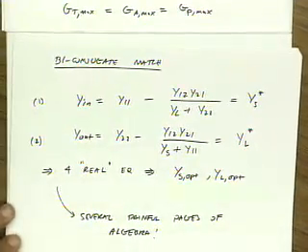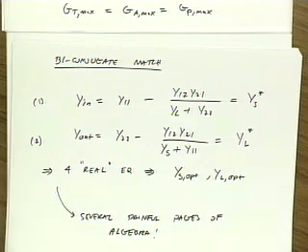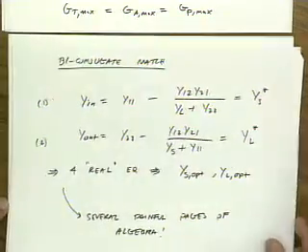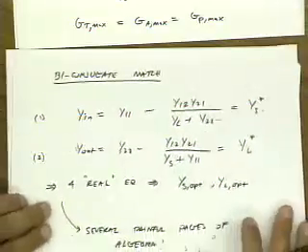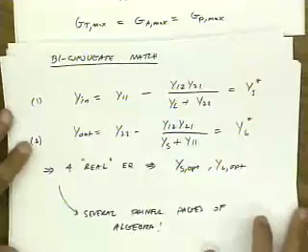When you're solving the equations, you'll run into a square root somewhere, and the square root has to be positive. That gives you the condition under which the solution exists, and that's exactly the condition we were talking about that could lead to oscillation if it's not satisfied. So this is one procedure for finding YS and YL.